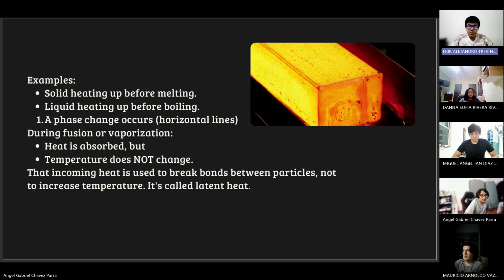A phase change occurs during fusion or evaporation. Heat is absorbed, but temperature does not change. That incoming heat is used to break bonds between particles, not to increase temperature. It's called latent heat. Now we are going to talk about the latent heat.